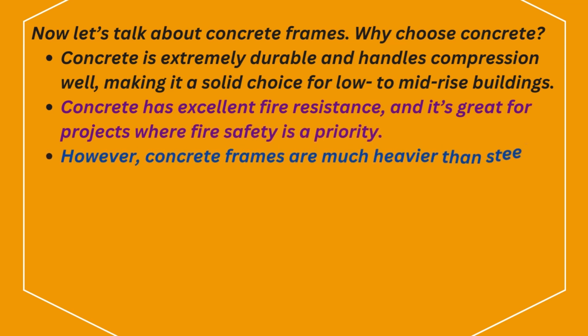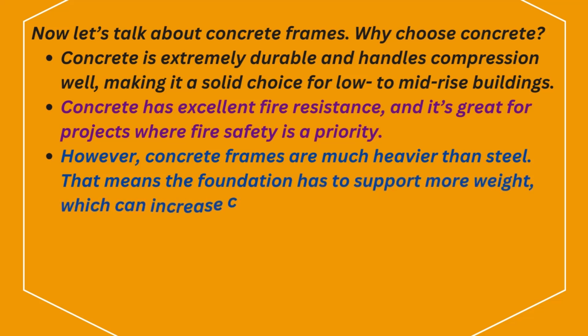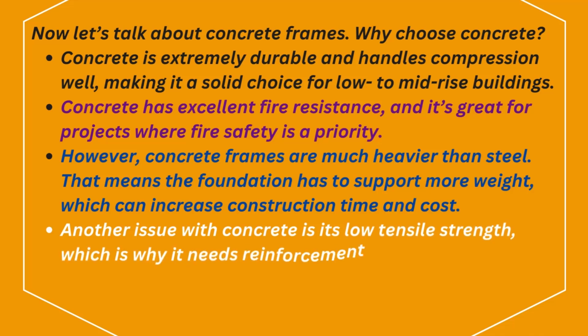However, concrete frames are much heavier than steel. That means the foundation has to support more weight, which can increase construction time and cost. Another issue with concrete is its low tensile strength, which is why it needs reinforcement with steel rebar to prevent cracking.